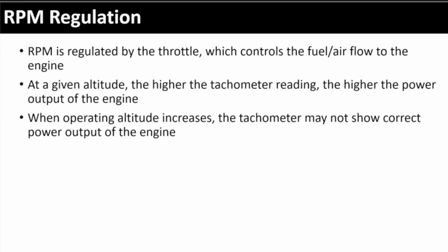Which means what? With every turn, every spin of the blade, what do you get? You get less power, less thrust, right? Because the propeller doesn't have as much air to cut through, right? So you lose not only RPMs because of the pressure or the density altitude change, right? The engine loses efficiency at higher altitudes. That leads to less propeller efficiency and less propeller thrust.